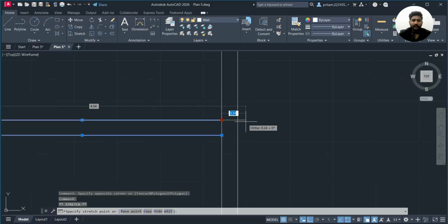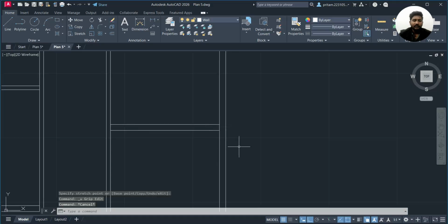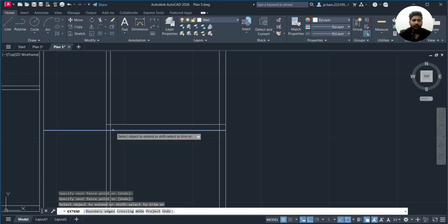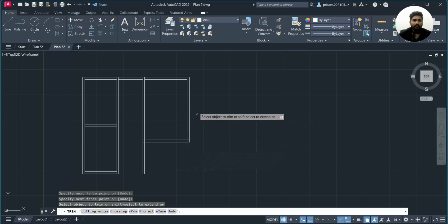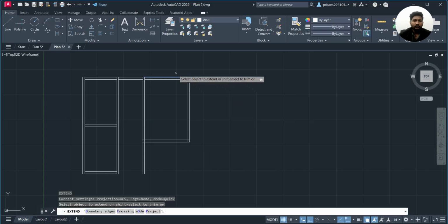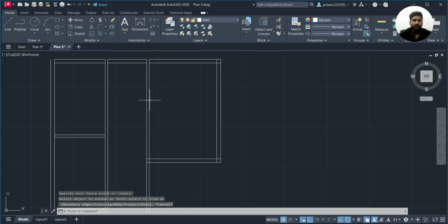Okay, we can just directly drag to this point here like this, or you press Control Z. There is a command present, that is the extend. Just type E, X and enter, and just drag here. You can see that the command has been set and it has been extended. Okay, and when you click on it, you can see that the further point has been seen perfectly. Okay, like this way it actually works. Trim this part, it is not required, and extend this part also. Like this way we have completed this part.